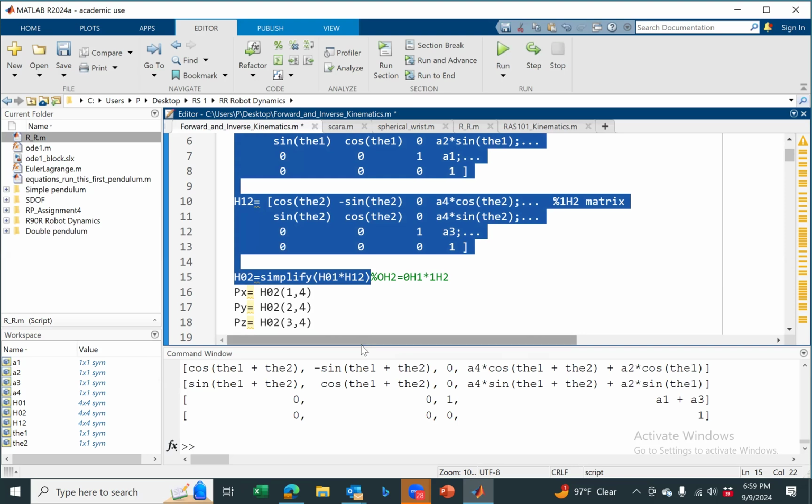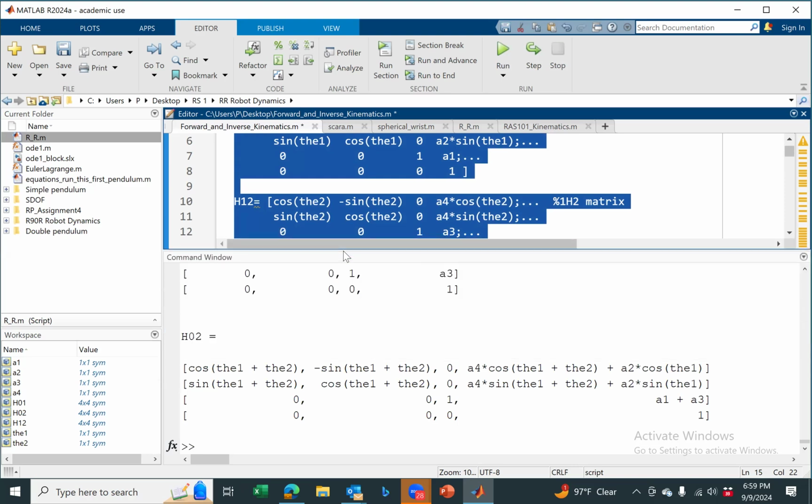So when I multiply the homogeneous transformations, what I have is extremely important. And I want you to try to see the physics, or the physical interpretation, of this equation. So the first 3 by 3 rotation matrix gives me the rotation of the end effector with respect to the base frame.